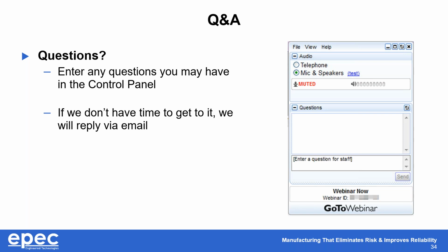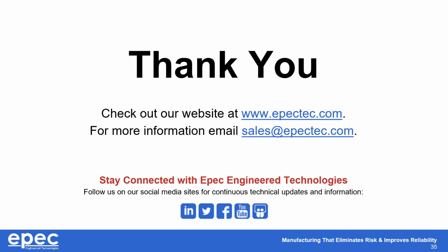If you try to take a 2 mil or a 1 mil piece of polyimide and run it without a leader through old rigid processing equipment, you're going to wrap that around a roller, right? So that's why it's important that if we understand what the application is, we can help you create the most cost-effective solution from a processing perspective. So that's why, on rigid flex, there's a whole lot more. We can do a whole Q&A session about that, but there are some additional things on the flex and rigid flex side.